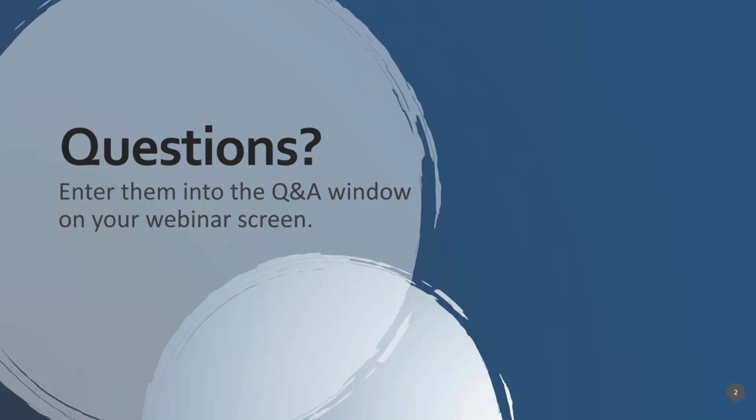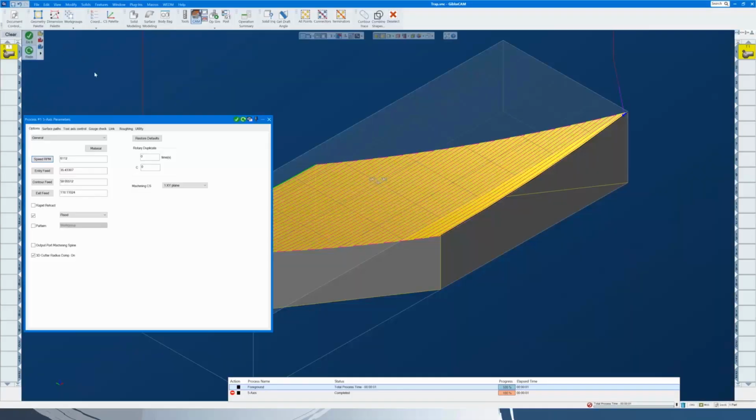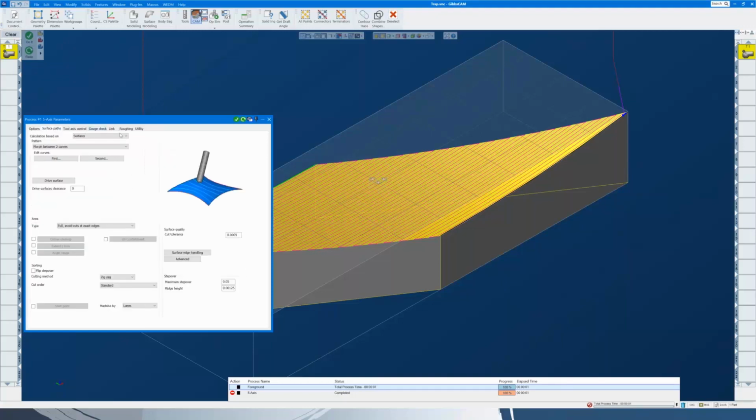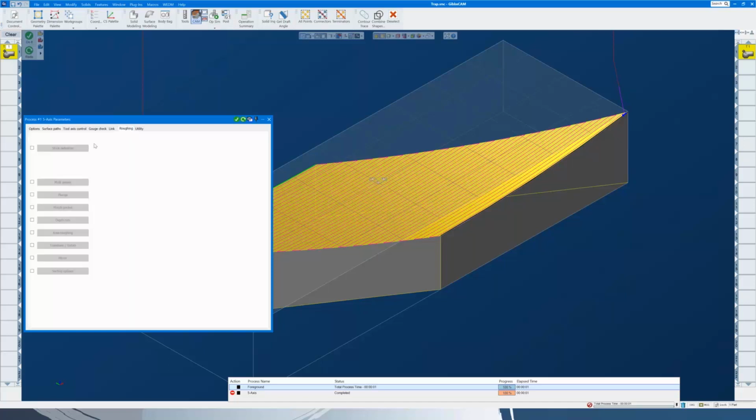Okay. Next question also for you. You showed finishing toolpath throughout your demonstration. Can the 5-axis module also do 5-axis roughing? Again, the answer is yes. Just real briefly, again, with almost any of the tool paths that we select on the surface paths page, we have a roughing tab where you can define roughing routines based on your stock definition, taking multiple passes, plunge roughing, morphing a pocket, depth cuts, area roughing, and so on.